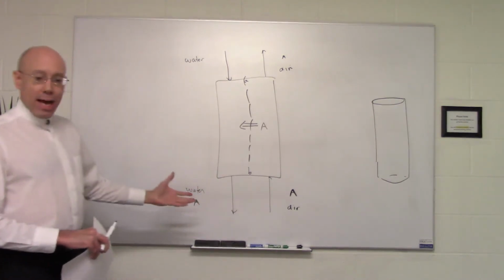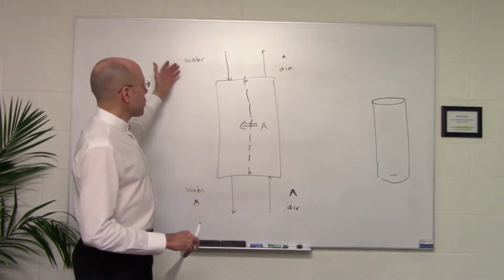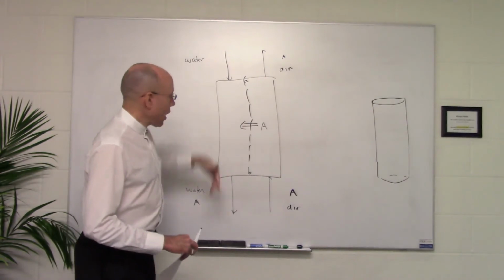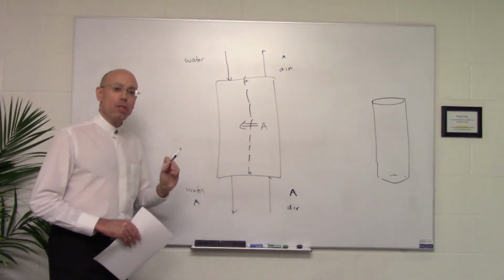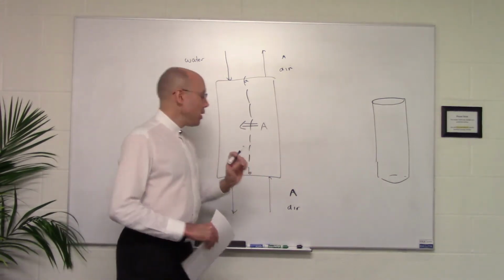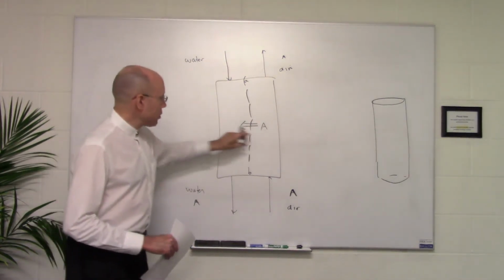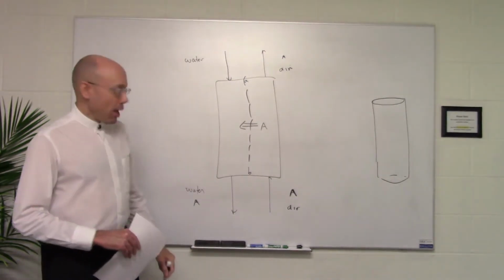So that's how gas absorption works. You pump air in at the bottom of the tower. Clearly water flows down, it's heavier, so you just pump water in the top of the tower, it flows down, and there's a lot of contact. I've drawn this as a wavy interface, a lot of opportunity for the ammonia, if it wants to, and it does want to, to get from the gas phase to the liquid phase. And so if some of the A moved into the liquid, it got out of the air, and there's less left, and the air got cleaned up.